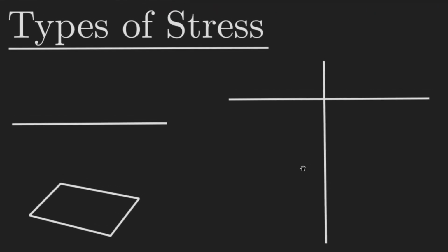It's the normal stress. But if you imagine, like if this is my area right here, there's two kinds of stress I could have, right? I could have it coming away from it. This is in the normal direction. Or it could be parallel to this. I mean, technically it can be in any direction, right? I could put a force this way. I could put a force this way. But I could always express this as a combination of forces that are perpendicular, either outward in tension, which is our convention for the normal, or it could be inward towards the surface in compression.